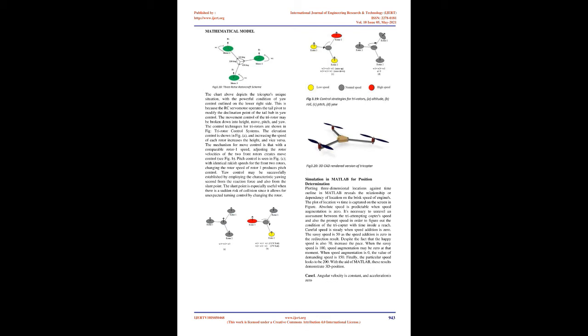Yaw control may be successfully established by employing the characteristic yawing moment from the reaction force and also from the tilt angle. The tilt angle is especially useful when there is a sudden risk of collision since it allows for sudden turning control by changing the rotor.